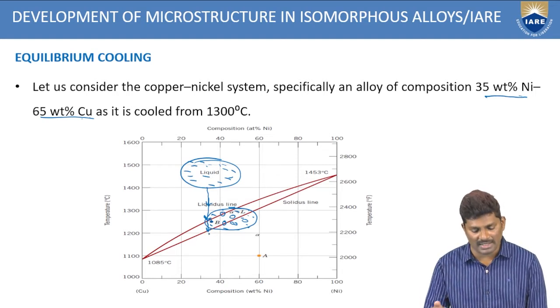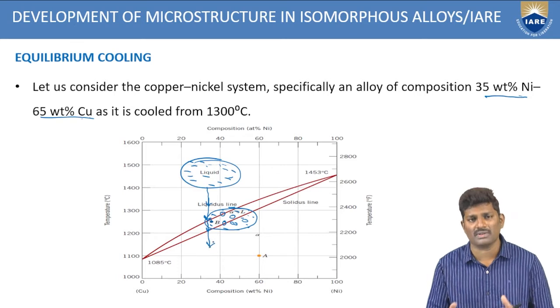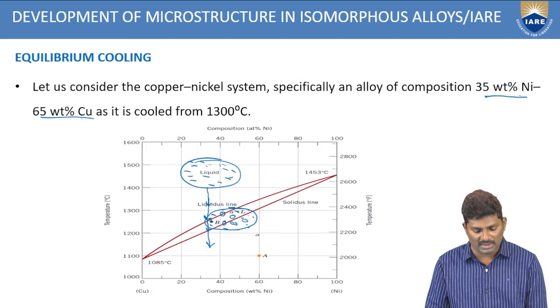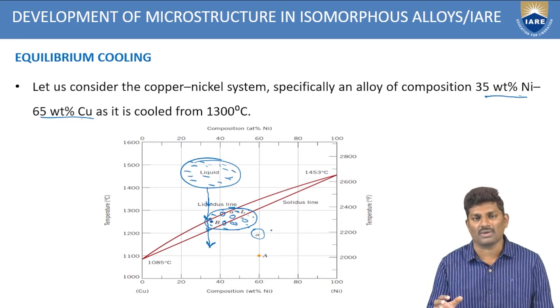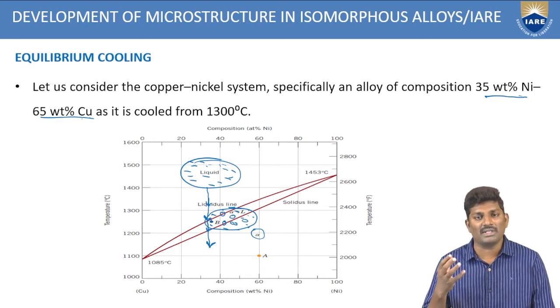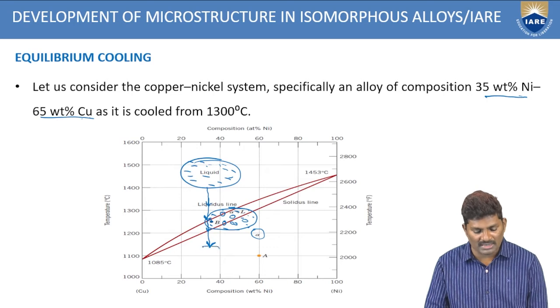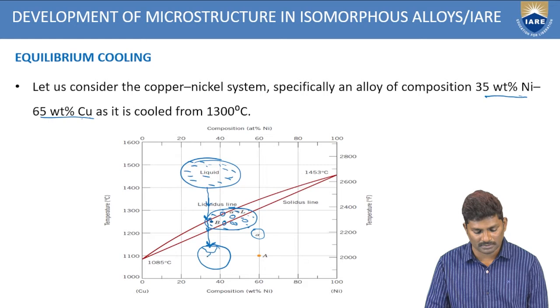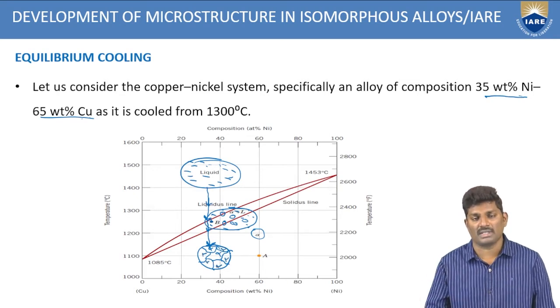And slowly, if you still reduce the temperature, that means you're trying to cool and get solidification of that material, it comes under the alpha region. So what is the alpha region? The alpha region is called the complete solidification region. If you again see the microstructure, you can find the alpha particles like this. So this is another microstructure you can see.